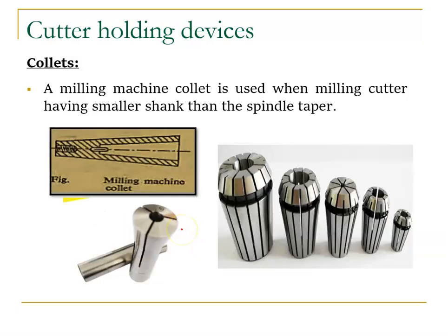So the difference is here, the bottom is a flat one, but instead of this bottom here we have a spring motion. Why do we use a spring? During machining, a large number of vibrations will occur. In order to prevent that, we need to use some absorbing element. So for that we use some spring collets.